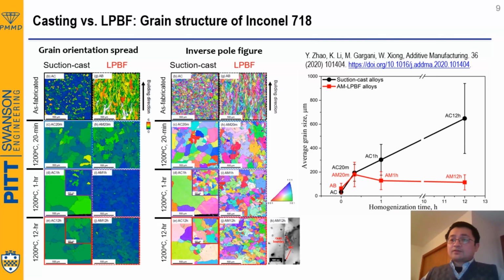But another thing that we have to take care of is not only the additive manufacturing itself, because all of this method that I described for the additive manufacturing part is actually focusing on additive manufacturing as-built alloys. Sometimes people can do post-heat treatment, of course, but once you run the post-heat treatment, then this developed gradient composition zone will start to diffuse. That's another challenge of utilizing additive manufacturing. How about doing something else using additive manufacturing? So this is the kind of question that we were thinking about.